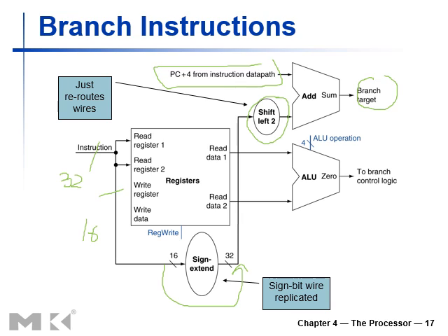Now, how are we going to assign that branch target address? That depends upon the zero flag. The ALU performs the subtraction, for example, S1 minus S2, and decides the zero flag. With the help of this zero flag and some dedicated control signals, we adjust our program counter depending upon whether the condition is true or false. So these are the primary components that we will use while using the branch instructions.